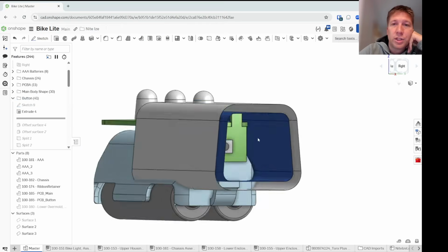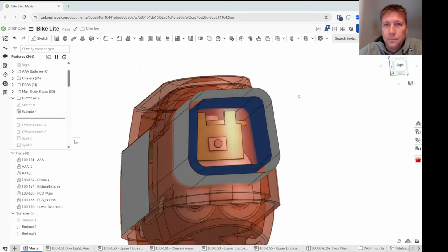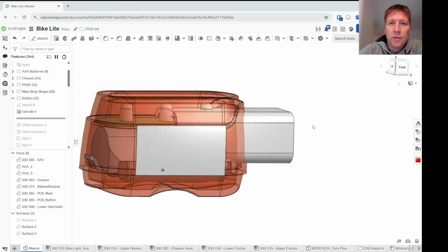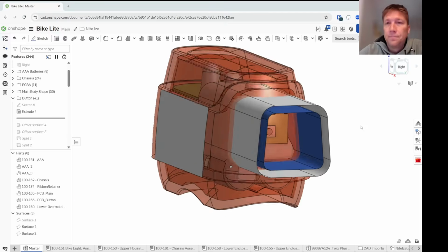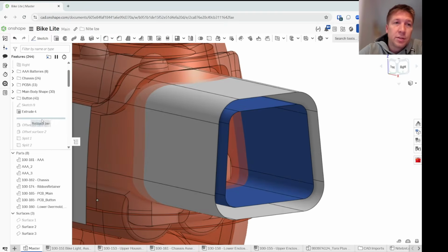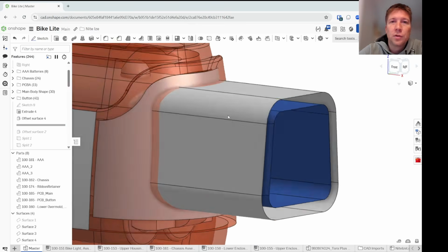And what I'm extruding is just two surfaces. So those two surfaces come all the way through the part, and those are going to become the inner and outer edges of my button surface. Next, I need a few more tools for trimming.